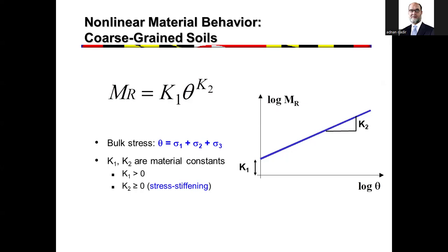If it had been a CBR test, as I was explaining, it was starting just from the origin. And if it was not starting from the origin, we were applying some correction. So this is not the case with the resilient modulus test. We do sample conditioning and then we start actually doing the test. So overall, you don't take 96 hours, but you cannot do it in some hours either. It still needs some time, first for the conditioning, then for the actual test, along with the sample preparation that we have to do.